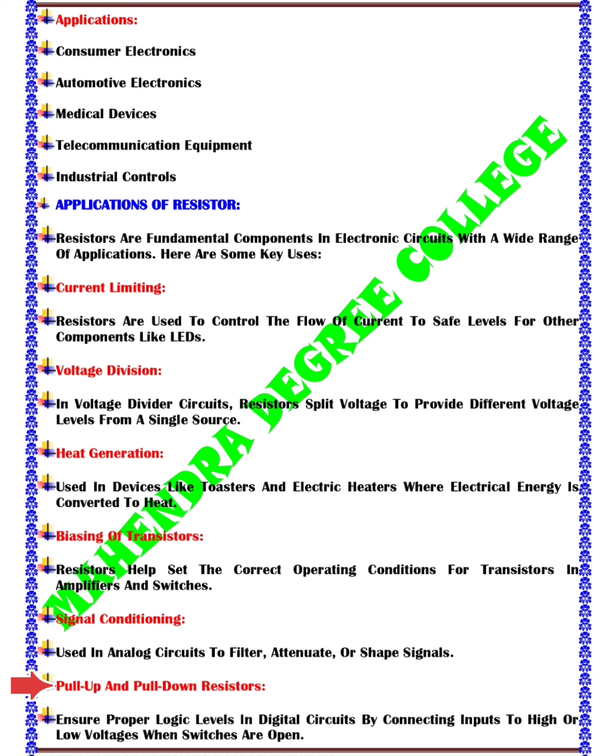It means pull-up and pull-down resistors are used in digital circuits to establish a default high or low logic state for input pins when there's no external signal. They ensure a defined voltage level, preventing inputs from floating and causing unpredictable behavior.